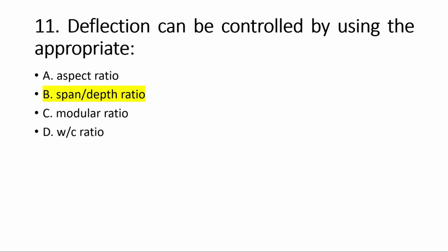Deflection can be controlled by using the appropriate span to depth ratio. So to control the deflection, we have to control the span to depth ratio.